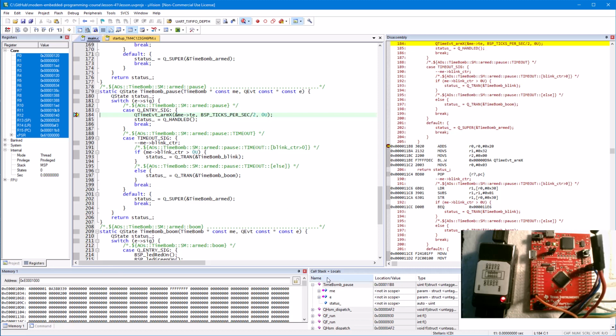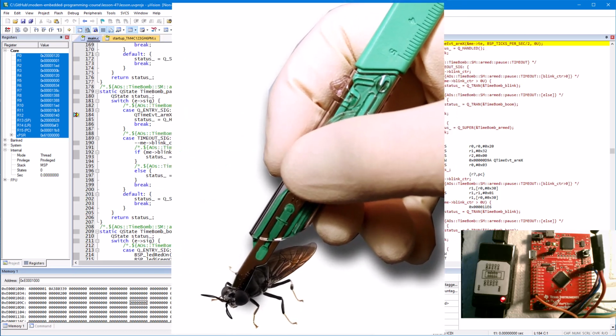The call stack might provide some help as to which functions were called in which order, but the information is minimal. In event-driven systems, specifically, the call stack is of less value because event handlers return after each event, thus removing any trace of their execution from the call stack. In the end, the biggest problem with a single-step debugger is that it stops the running system and completely changes its real-time behavior. It's like trying to study a living organism by first killing it.